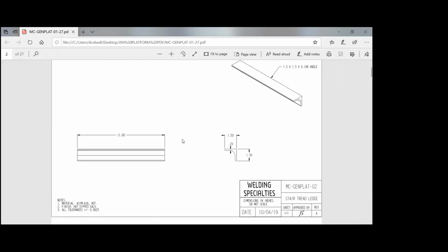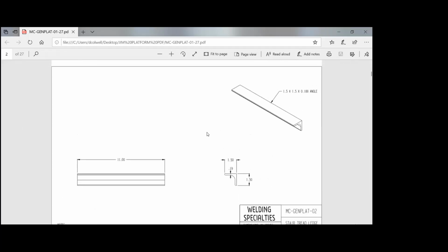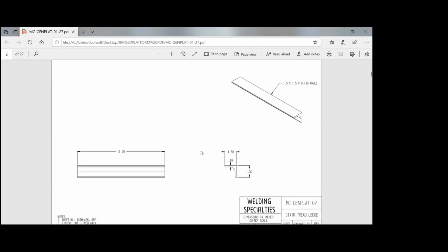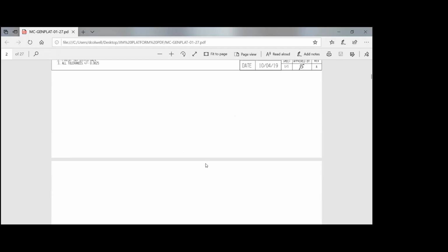There are plenty of free ones available, and then you can at least get this 2D shape and then extrude it out or something like that. But if you don't show radii on your drawing that are actually going to be on the product because it's a structural shape that's produced that way, it may lead to some confusion.